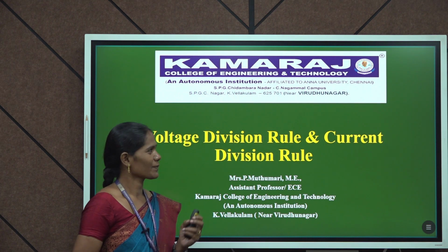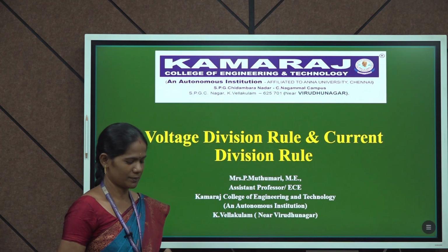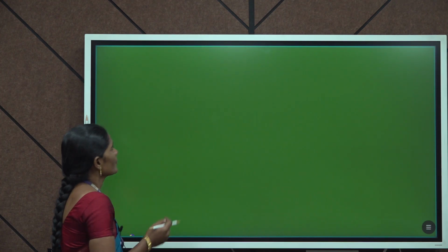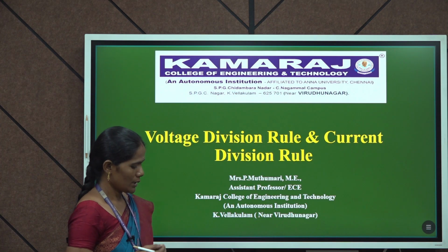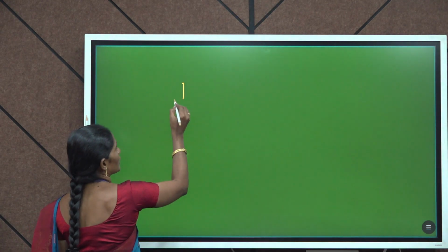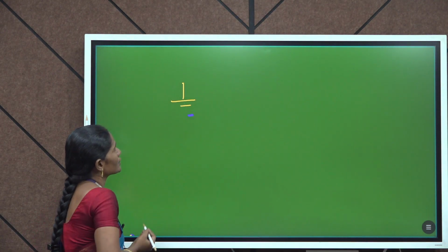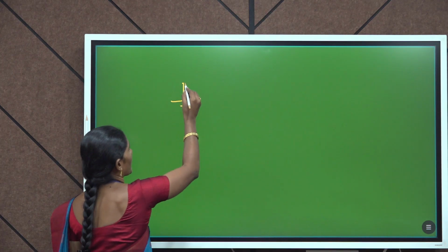In this video, I am going to discuss voltage division rule as well as current division rule. Wherever voltage is divided, we go for voltage division rule. When the voltage division occurs, the series circuit acts as a voltage divider. So, let us see this voltage division by using a small example.